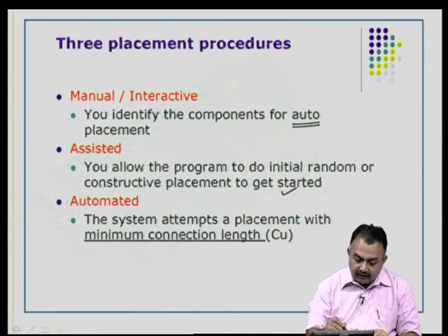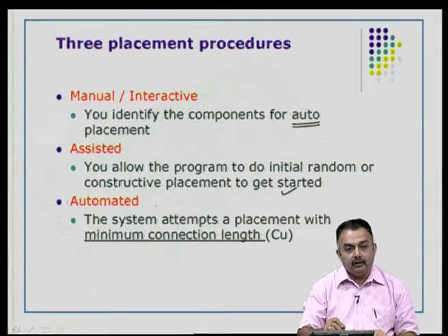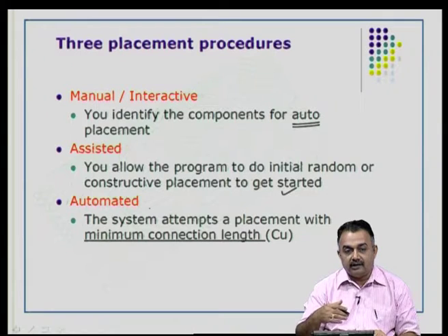Now, finally, if you are not interested in manual or assisted, then you can do automated, but experience always says that you had better learn to do manual placement, because you know the circuit better, you have done the paperwork, and you know which component needs to go where and which component needs to be close to which device.